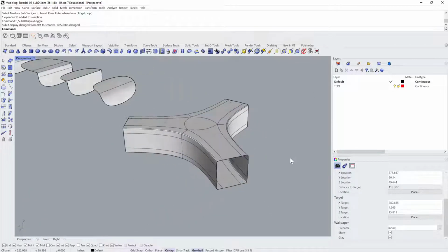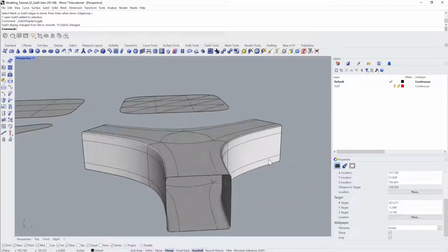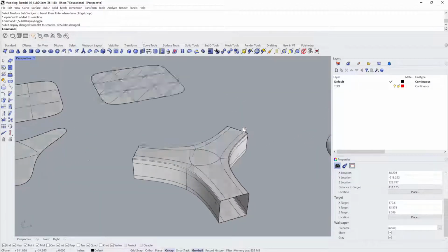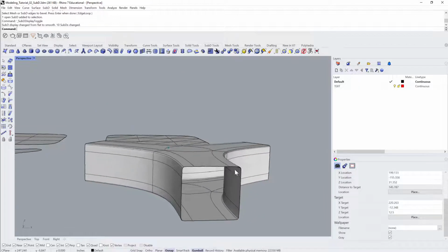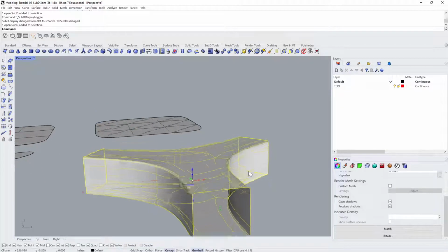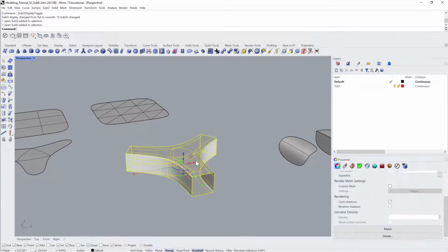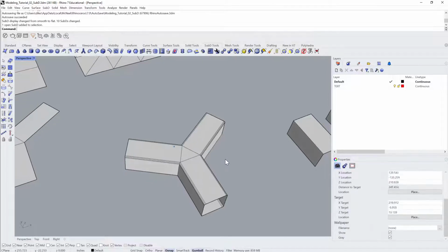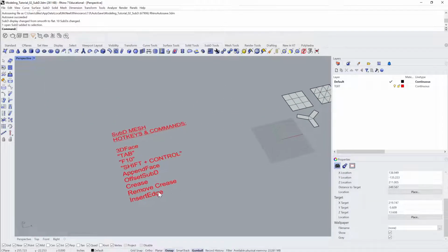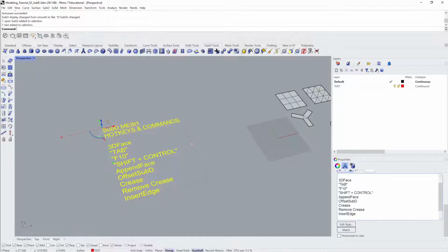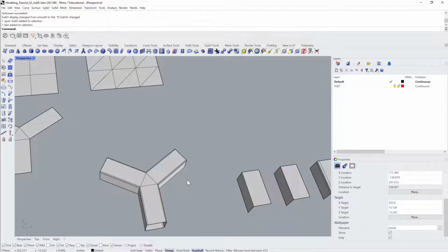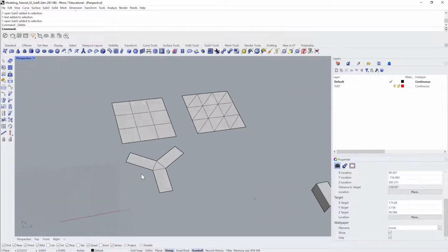And now let's hit tab. And now you can see that I've changed the way that this object smooths, and it's really clean, and we get this nice box-like shape. So we have rounded corners on this thing instead of just a rounded tube like we had before. So that's really nice, and it'll show you how you can use the edge flow. So that was Bevel. But InsertEdge is useful, and I'll show you a better example. That's the trickier example because we have this triangle in the middle, and that makes things tricky for our topology.